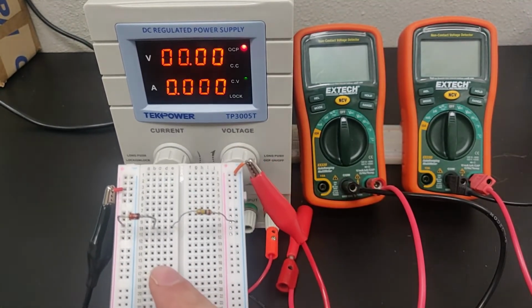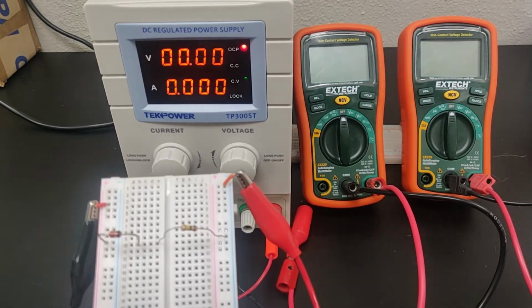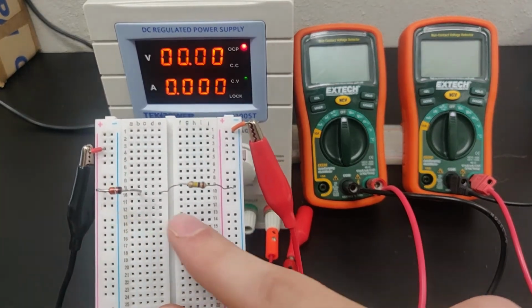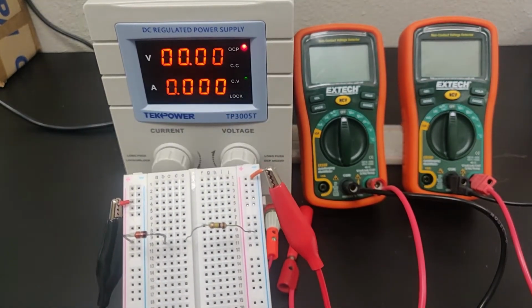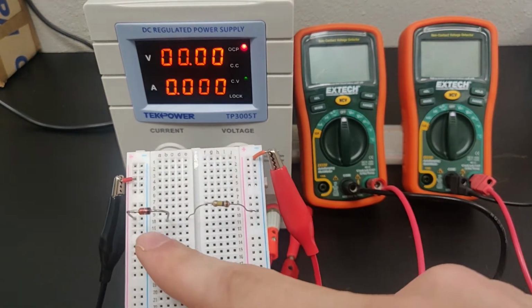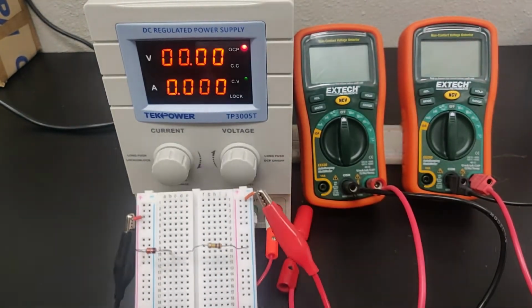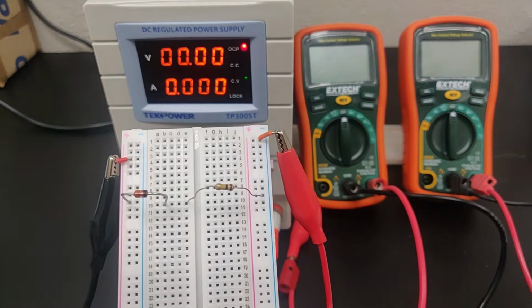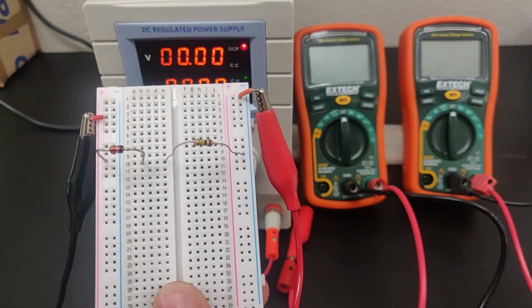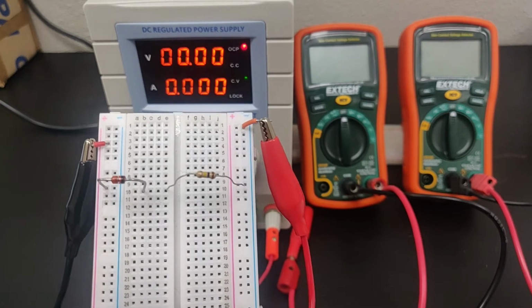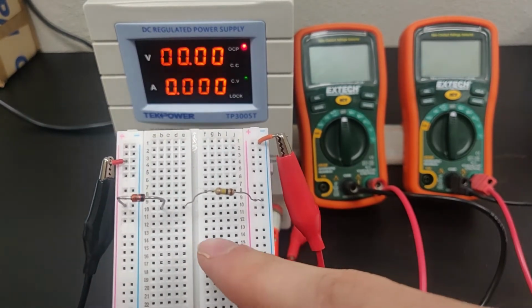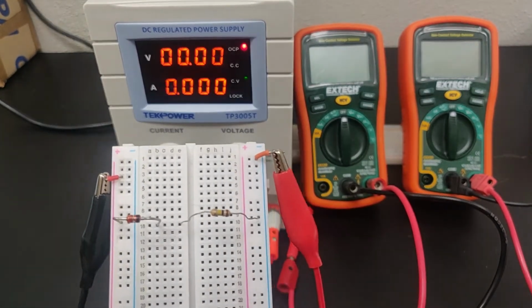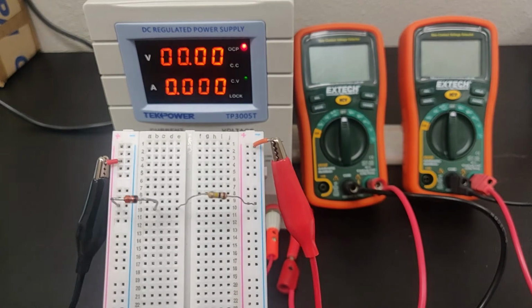And in this section, we are once again going to be creating a reverse bias circuit and going through this process of measuring the voltage drop over our diode and our resistor so that we can create this characteristic plot of the voltage versus the current for our diode. The difference now is we are using a Zener diode as opposed to the signal diode that we were using in the previous section. And we are only going to be measuring the reverse bias orientation because the forward bias is essentially the same as the signal diode, so there's nothing too interesting there.